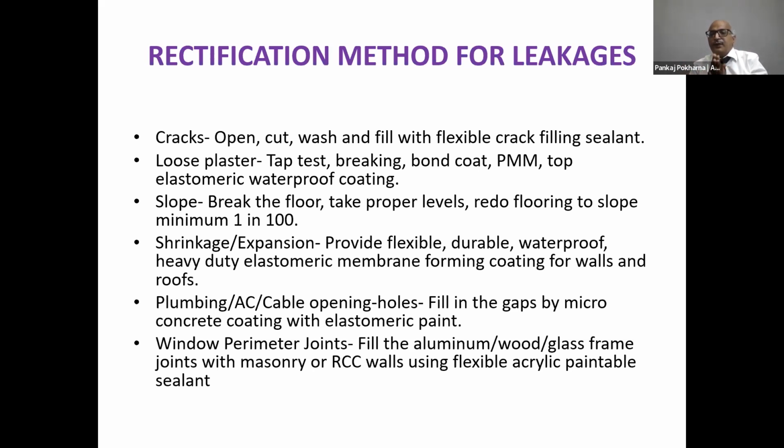The second point is, after cracks, when you check the areas near the cracks and tap, sometimes you find a hollow sound. When you find a hollow sound, you find that the plaster is hollow, loose, debonded, and it comes out easily. Somewhere it has already fallen or broken, or sometimes it comes out when we check.